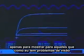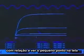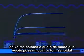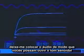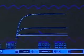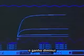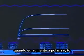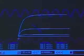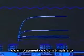Just to show this, for those like me who were visually challenged in viewing that little dot out there, let me get some audio so you can actually hear the sinusoidal tone. It's a bit annoying. So as I reduce the bias, the gain is decreased. As I increase the bias, you can see that the gain is increased and the tone is louder.